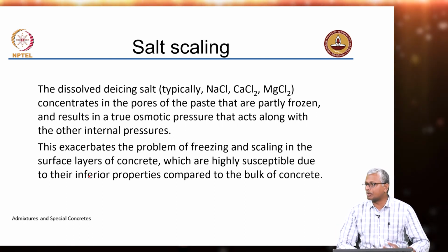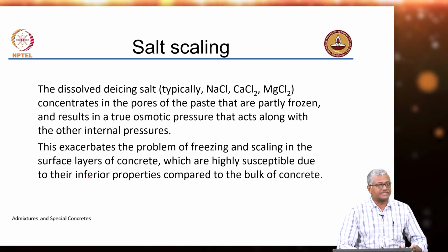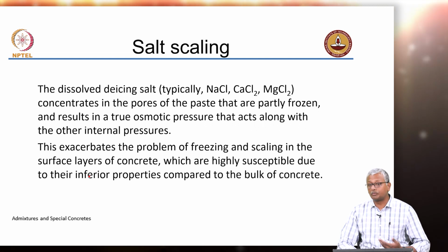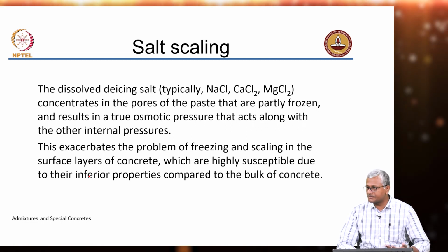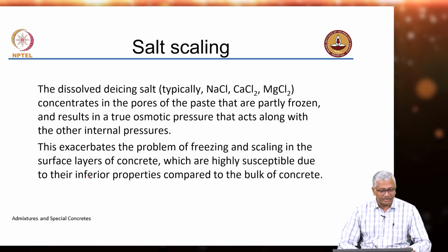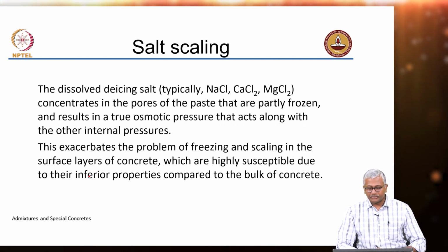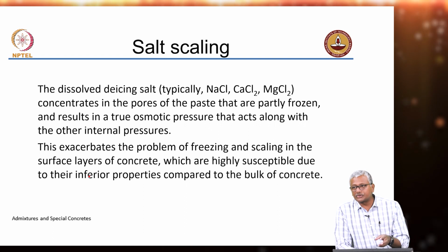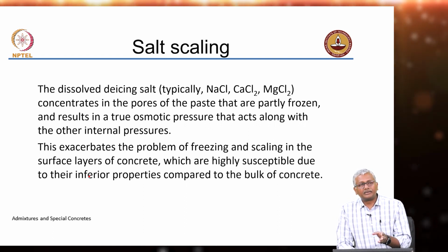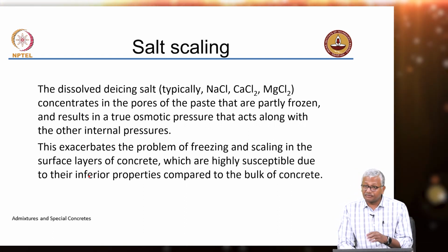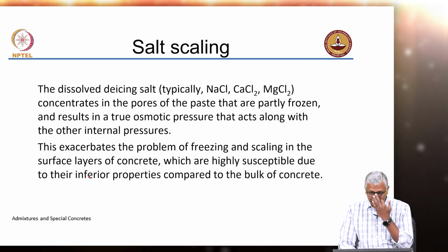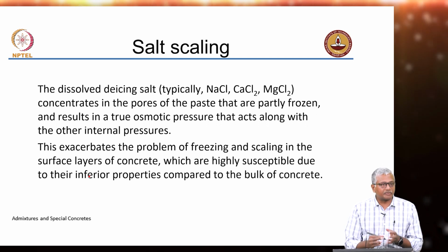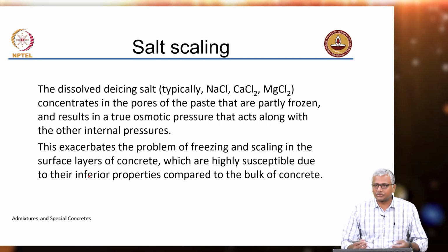This is a realistic problem in many of the pavements in Western countries, where they put salts on the surface of the pavement to prevent any skidding of the vehicles, right. So, there is a lot more additional literature on salt scaling that talks about the performance of concrete with different binder systems, which is a fairly interesting subject to look at, but we do not really worry too much about this because we do not have this problem in most of our places.